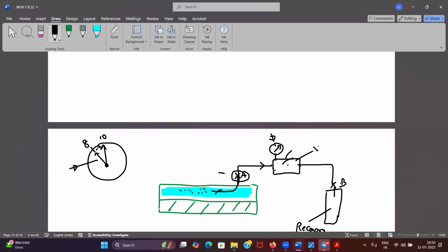Okay, if you don't mention the vacuum pump, then the surveyor might not accept your answers. Normally we do not use all this on the ship. We directly connect it to the recovery bottle, open it, and as soon as pressure comes once, we close it and remove it. There we are not caring much about a little bit of leakage. But when you tell it in front of the surveyor, he will catch you here, right? This is your actual practice, that you have to use the vacuum pump. You have to create vacuum in the pipelines before disconnecting these pipelines. Is it clear?